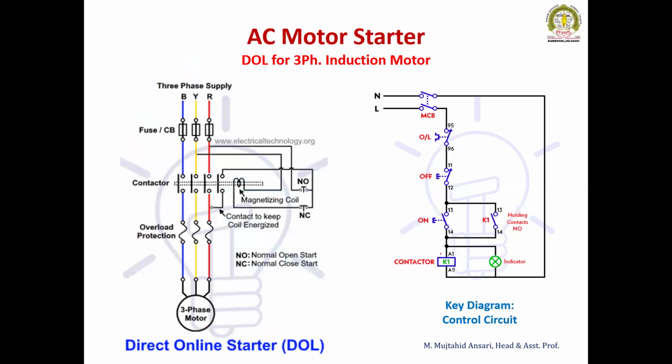So next is the AC starter, the AC motor starter. Generally, one is called a DOL starter. It is nothing but direct online. Online here does not mean what it sounds like. It means we are not providing any sort of voltage reduction at the time of starting.